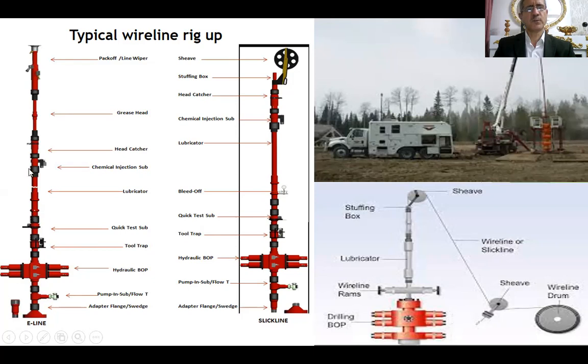It should include the maximum length of the tool string in the well. We have also here either single or dual BOP. It should be a minimum of 2, which is dual, or double 4 rams.